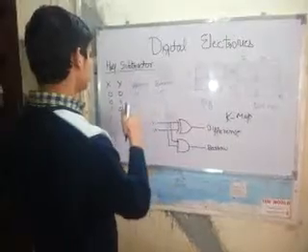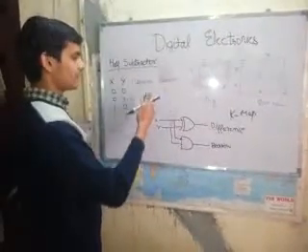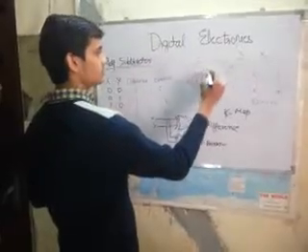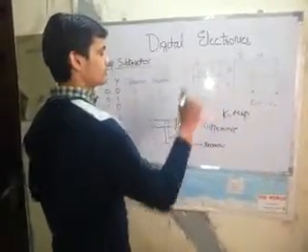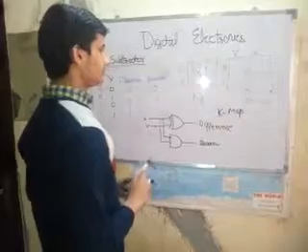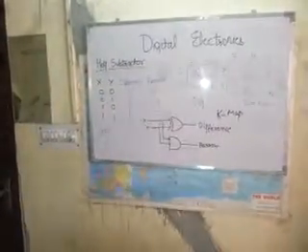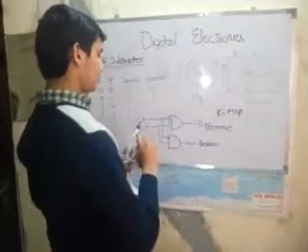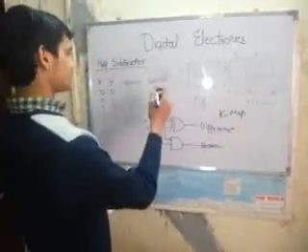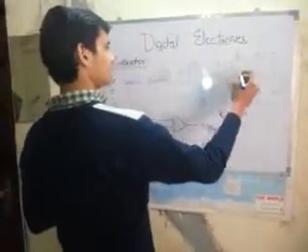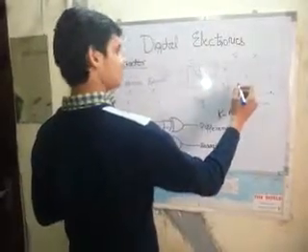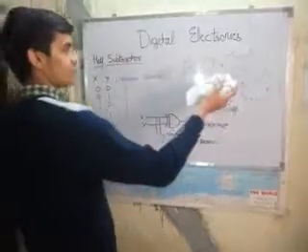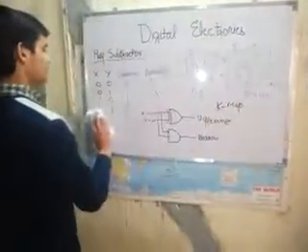So now this is x and y difference. We have to construct the difference K map. The difference K map is like this. This is 0, this is 1, this is 1, and this is 0. Let us first fill the borrow also. For borrow it is 0, 1, 0 and 0. Okay, so now we have constructed the K map. We will now construct equations for that.